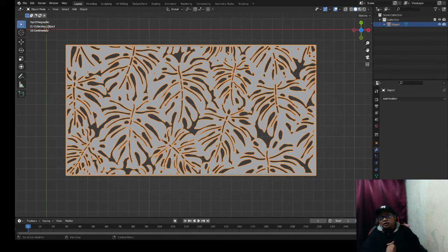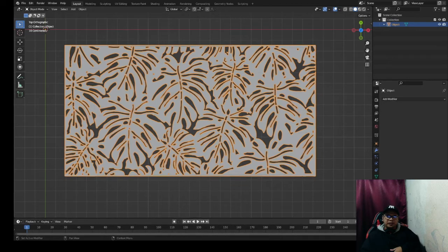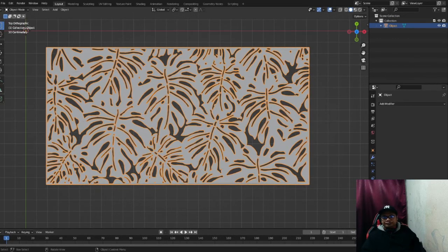All right, guys, this is our last step. We have successfully now imported our models to Blender, and the reason why we are importing it to Blender is because we want to give it a thickness, because the FBX that was exported from AutoCAD doesn't have a thickness. It's just plain. Usually our clients or your boss or real world materials do have a thickness, like 0.07 inches, 0.03 inches, or one fourth, like that. No, 0.07 feet, like that.